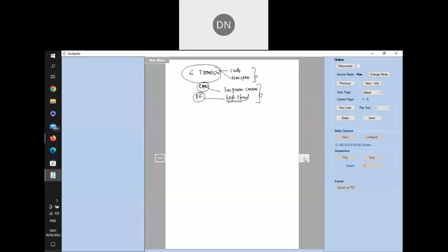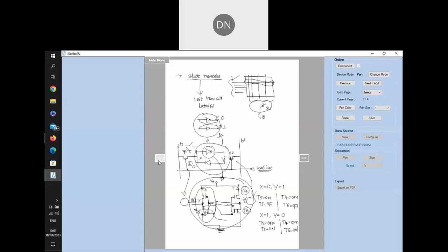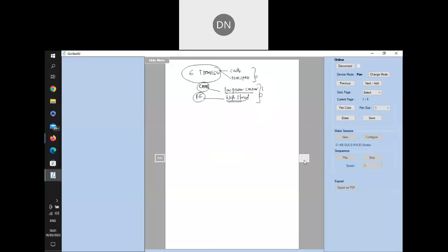Since CMOS technology is used, we have seen in the previous circuit that whenever the cell is not selected, the T1 transistor is off, the T2 transistor is off, and in each inverter one of the transistors is always off. There is no active path between the power supply VDD and the ground when the cell is not selected. When the word line is not selected, there is no path for power to pass from VDD to VSS, the ground. That means power consumption is very low in a CMOS circuit. So this is an advantage, the low power consumption. The only disadvantage is that it's costly and requires more space because of the 6 transistors.